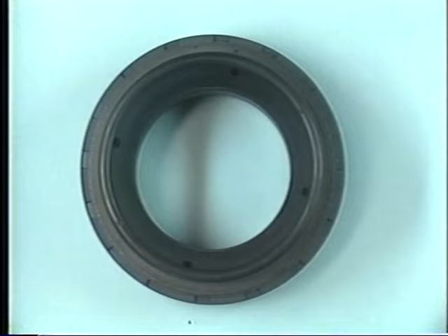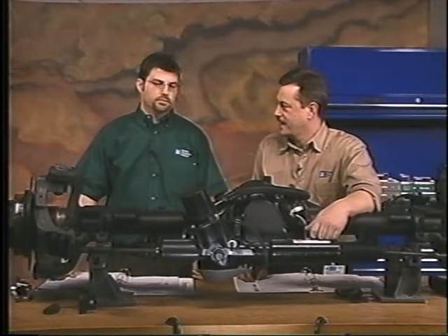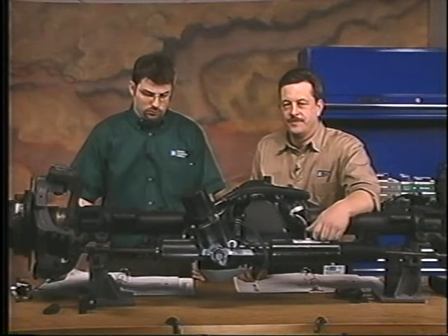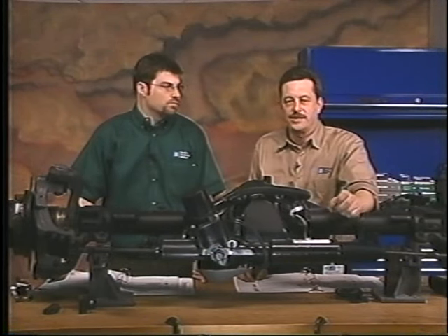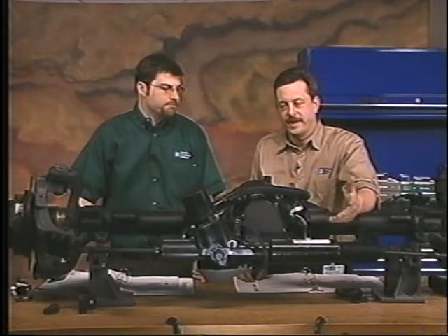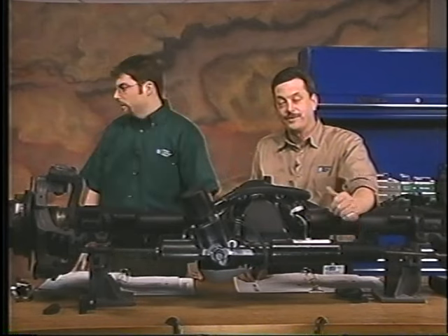It is very complex. We're going to have to disassemble the rear axle here. Obviously, got to pull both axle shafts out. Then, once we get all that out of the way, we can go ahead and pull those seals out from the inside. To reinstall, you need the small block V8 cam bearing installer. That's the tool we're going to use. But it sure sounds like a lot of work. Yeah. Hopefully, you don't have to go there.